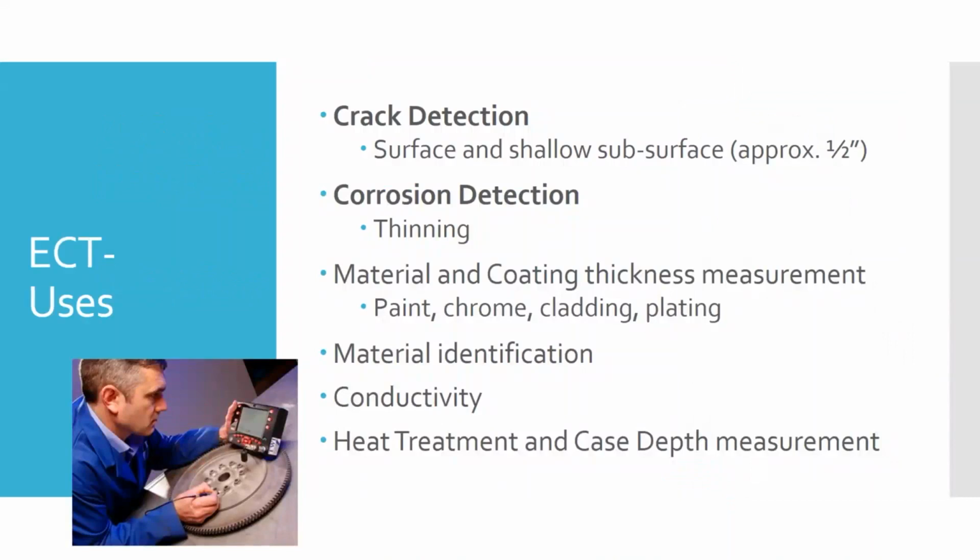So eddy current testing, what it's used for, it's primarily used in aviation for two things. The first is for crack detection, and it can detect primarily surface, but also some shallow subsurface cracks, up to cracks that may have occurred about a half inch deep.